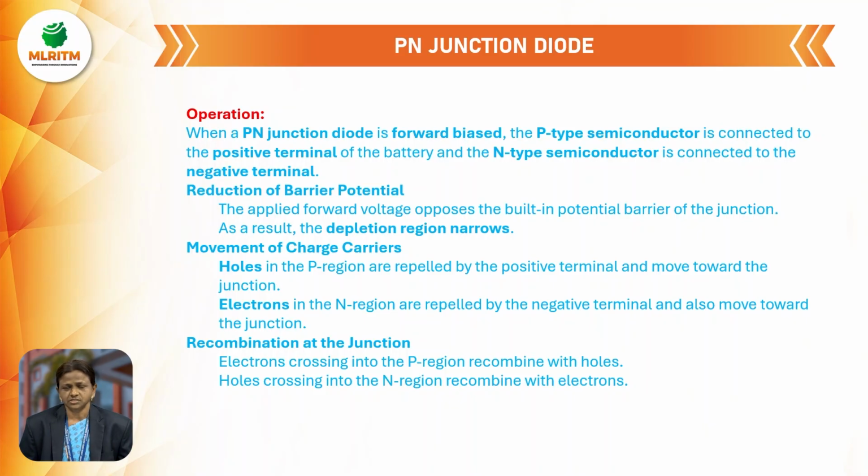So in this aluminum, by using these 3 valence electrons, 3 covalent bonds are formed. What about the fourth one? The fourth one is nothing but vacant space. This is known as a hole. So it is in a position to accept one more electron from the neighbor atom. That's why these p-type materials are known as acceptors.